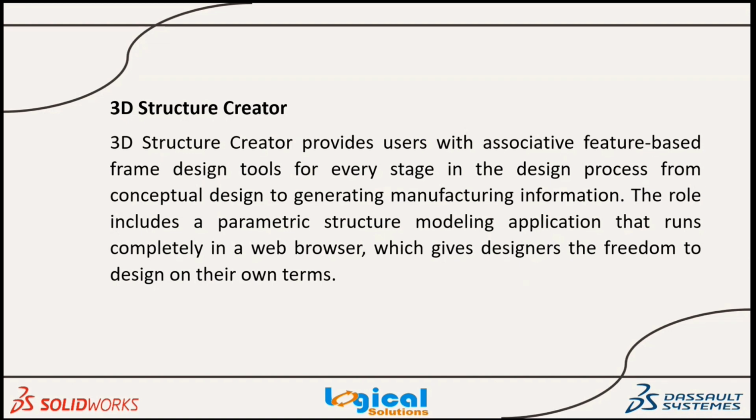With the 3D structure creator, you can create structure members based on model edges, 2D sketch elements and curves. And also we can choose profiles from the library of the standard types and sizes. Here in the 3D structure, the best thing is we need not trim or extend the things. The software automatically trims members at the endpoints and corners, and the automatically generated cut list is based on the design used for fabrication. And we can also increase productivity with a streamlined structure design workflow and a dedicated design environment.